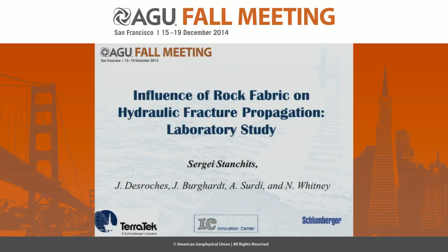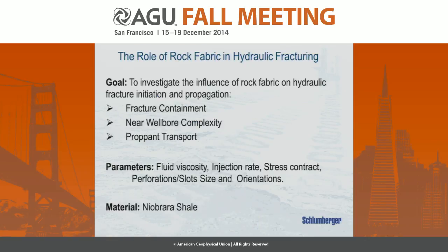We performed a series of laboratory tests to investigate the influence of rock fabric on hydraulic fracture initiation, propagation, and the near wellbore complexity. In the frame of our long-term project, we varied different parameters like fluid viscosity, injection rate, and completion geometry. We changed the size and orientation of wellbores and also perforations, and performed long-term research in this direction.